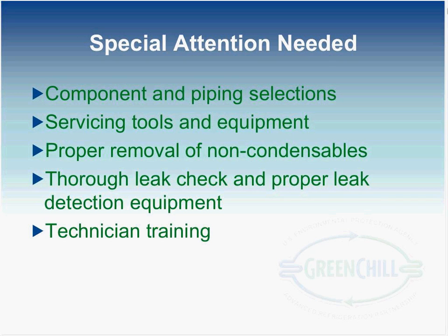With the cascade system, similar to that of a standard DX system, the biggest challenge is with a good refrigeration technician being comfortable with the pressure levels, as well as being able to troubleshoot the system during operation and avoiding refrigerant trapping by use of isolation valves.